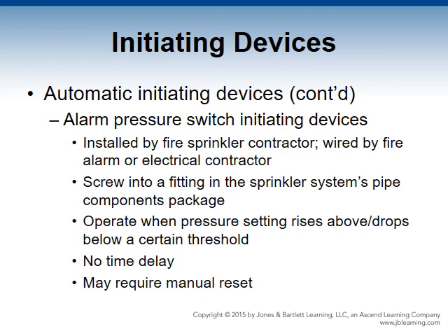When they reach the threshold, the alarm signal is sent to the alarm panel. The switch may require manual reset. This type of switch is best for dry pipe, preaction, and deluge systems, wet sprinkler systems with recharge chambers, and other types of water-based fire protection systems.